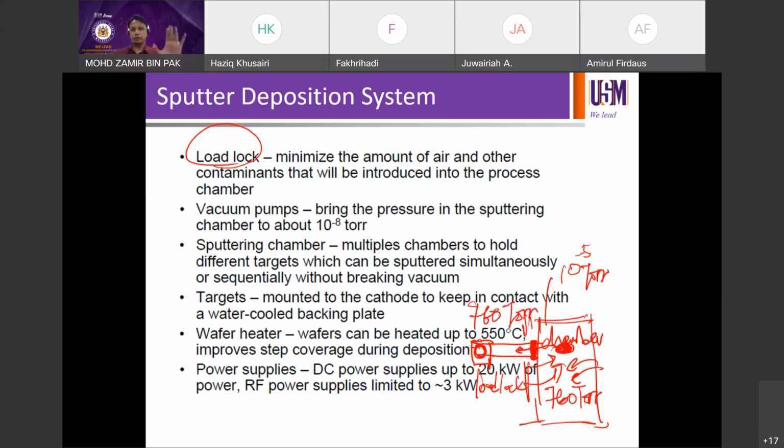And that will reduce contamination to the main chamber, because the load lock is not the main processing chamber. It's just a mechanism to transport your wafers and your other samples. So you vent the load lock to 760 torr or 1 atm, then you can take the sample out, while the chamber is still at 10-5, because there is a gate valve isolating the chamber and the load lock. In that case, you maintain the purity and cleanliness of the chamber.